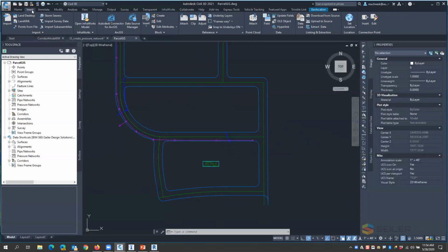One of the downsides to it, and it's getting better and better every day, or every release or every update, a lot of times we have to deal with working with GIS systems that already have a predefined feature class list and predefined attributes. One of the downsides of the previous versions of it is exporting and creating a file geodatabase from Civil 3D products or parts were the attributes were set in stone.